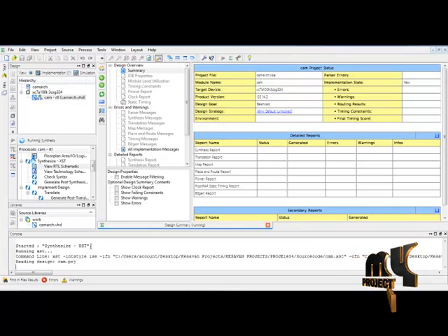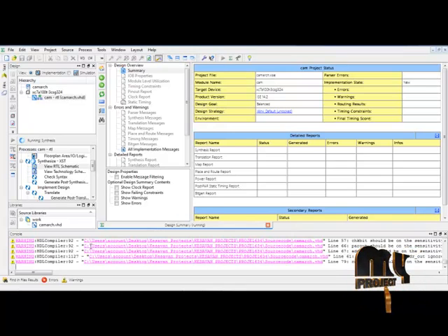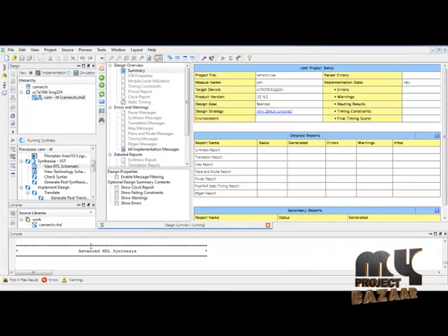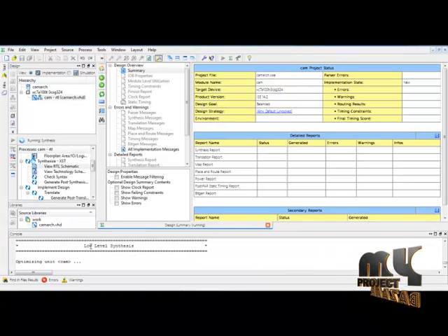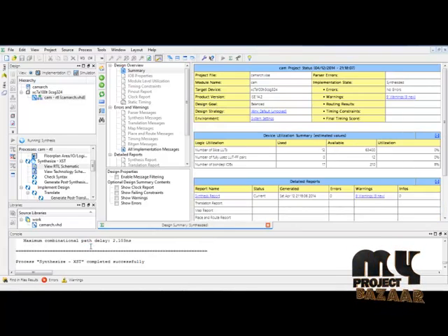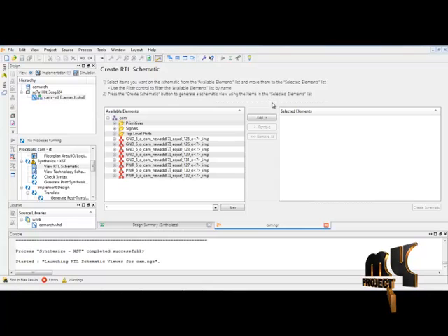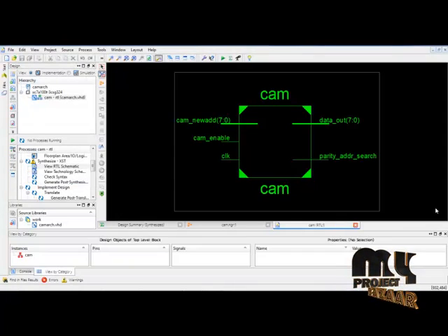This also checks the total number of LUTs and flip-flops which are present in the logical design. The RTL schematic design will display only the schematic architecture of the logical operations which are provided in the coding. In this case, just click Add and click the Create Schematic button.